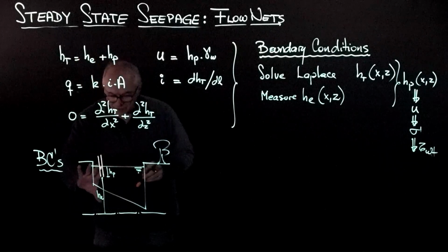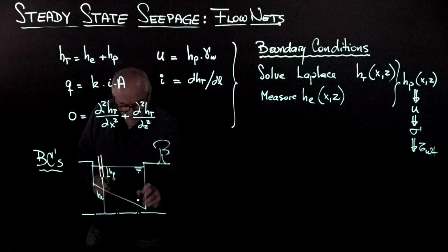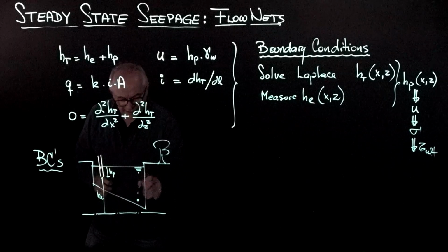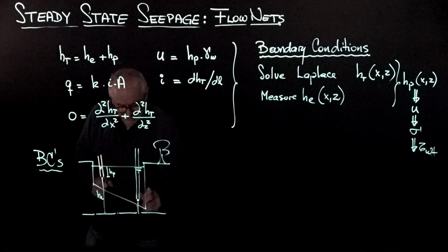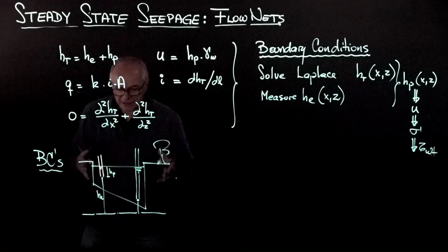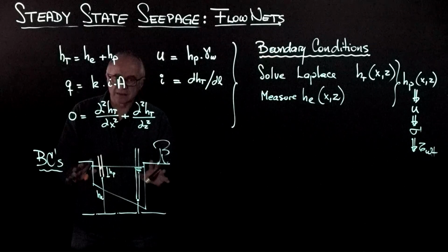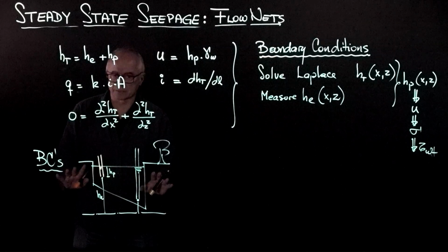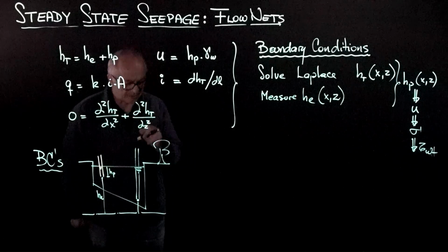And the sum of these two is the total head at that point. Now I can go to the bottom of the swimming pool, and once again I place a tube, and by the same reasoning it will go to the top of the water, and this is the elevation. And you can readily convince yourself that in a swimming pool the total head is constant everywhere. This is a good one to remember.